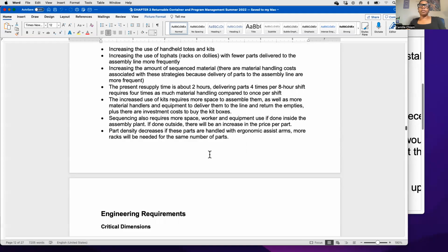say, if you are feeding in parts that are installed by a robot, because the robot is programmed to pick from a specific area. And if the packaging, for whatever reason, is not repetitive, or it's not precise, then the robot will have trouble locating. They won't know where to go. They're like, well, I thought it was over here, but it's not. It might be over an inch or two. So that robot will keep missing that part and won't know what to do.